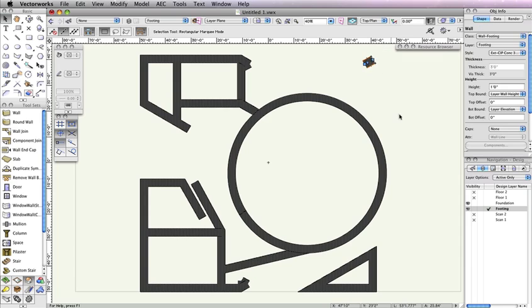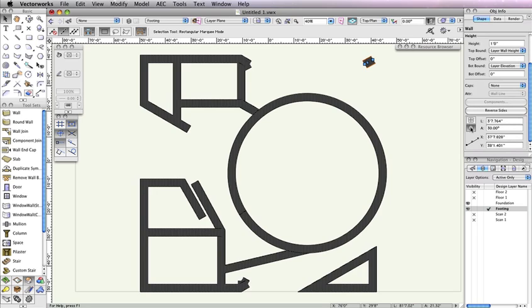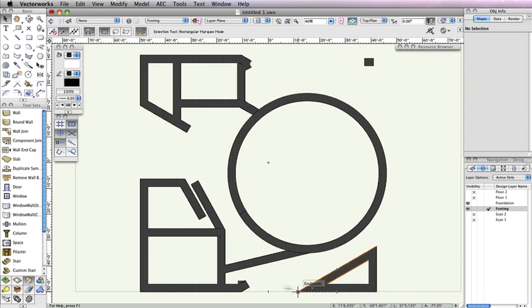Now, select the wall that remains and go to the Object Info palette. Click the Polar Grid button at the bottom. Next, choose the center position point and change the angle field to 180 degrees. Now the wall should sit horizontally. Now let's fix the area with the overlapping walls toward the bottom of the building. Delete the 2 walls that are not joined to the adjacent horizontal wall.